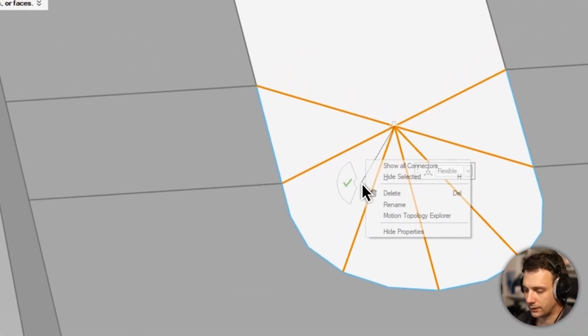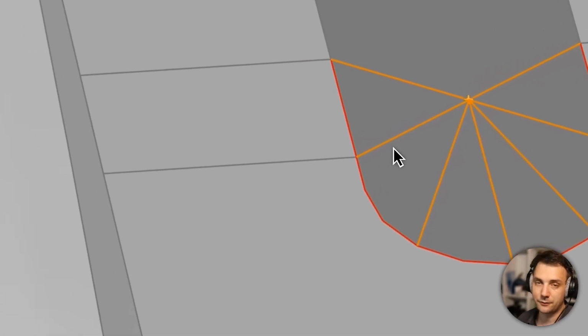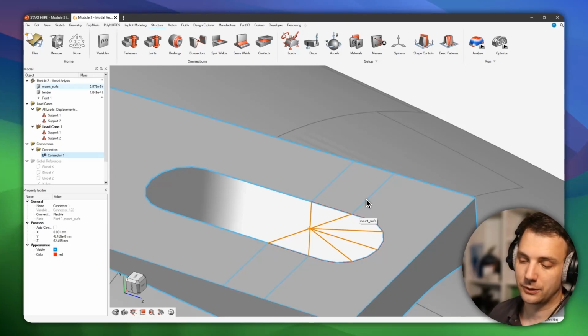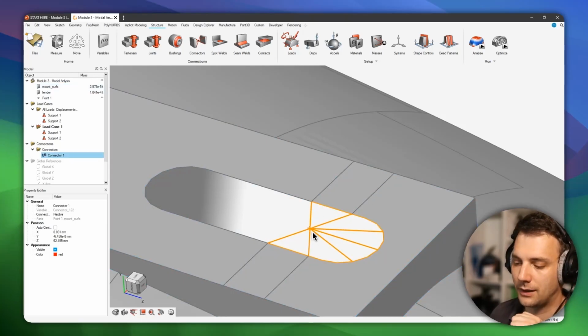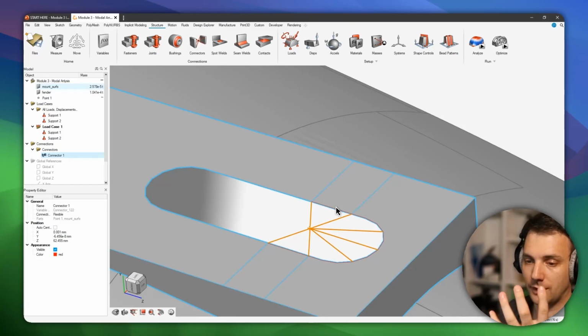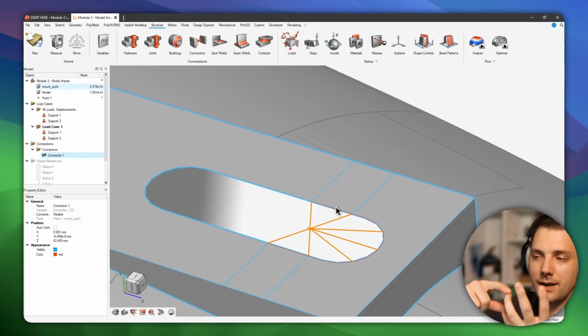Okay, I think that's all right. And you see that it says flexible. So the difference between flexible and rigid is that if you do flexible, the points, not here, I will call that master, and those are the slave points. The slave points, they can move relative to each other, and there's no constraint with it. With rigid, you say, like, if you just use the hand as an example, the fingers to each other cannot move. They have infinite stiffness, and that's not right for here.